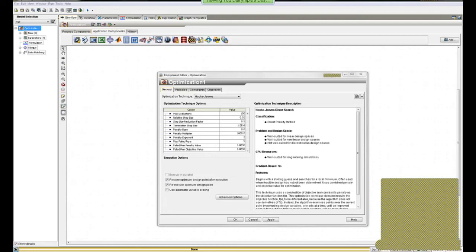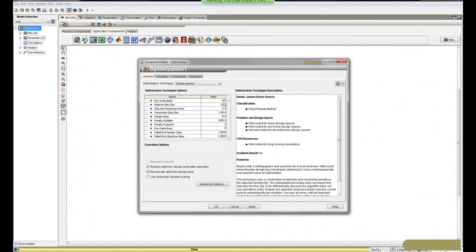optimum material parameter? I can imagine we would, but at some point you get too many design variables, and the problem becomes completely not unique. There's going to be a whole problem here of uniqueness. So I could imagine adding more and more design variables like the bulk modulus, like friction, but I certainly have to be far more careful about the non-uniqueness and whether I'm really getting the answer I'm looking for, or just another different answer that happens to match the test data. And I typically would approach that by trying to have multiple pieces of test data and dividing them using a kind of divide and conquer approach of matching one piece of test data and then another.